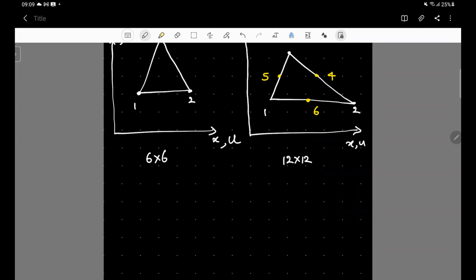There are 6 nodes, and each node has 2 degrees of freedom, so 12 by 12 matrices have to be tackled or developed when we talk about stiffness matrices in connection with the LST elements.